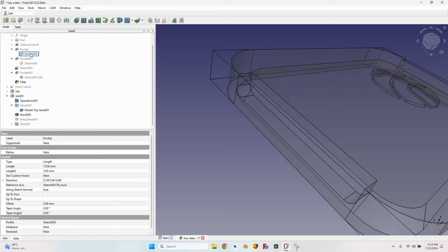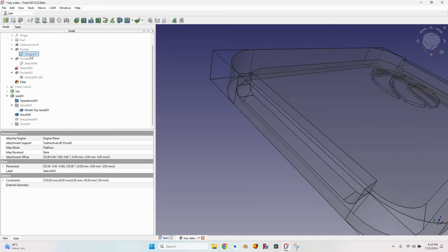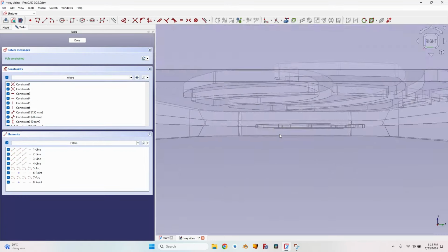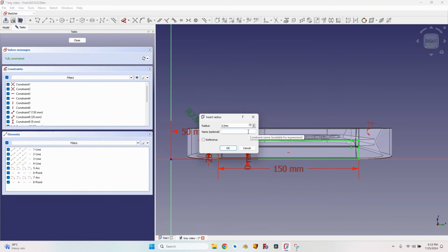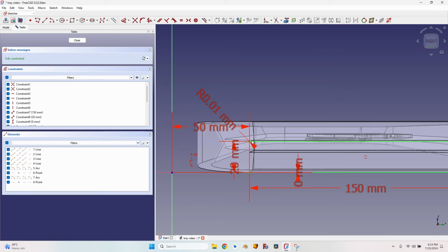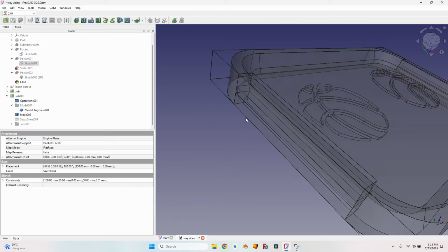In the 3D pocket operation it will also give you an error, so you have to rely on some little hacks. Go to the pockets that define these two handles, open the sketches and modify the radius of the roundover from 7.95 to 0.01 millimeters. Close the sketch, open the second one, also modify the radius to 0.01. I modify the radius because I don't want to simply remove the roundover and make the points coincident. It's much easier to modify later.